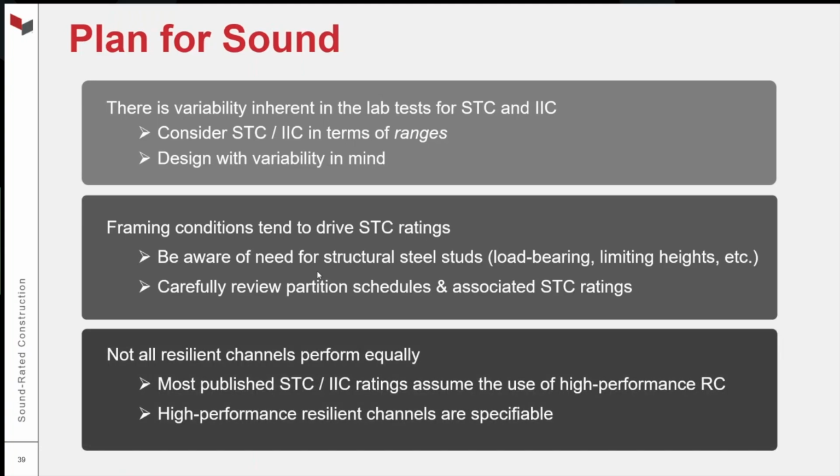And as I mentioned before, when we took that little side quest talking about resilient channels, not all resilient channels perform equally. A vast majority of published STC and IIC ratings assume the use of high performance resilient channels. So anticipate that. And if you're on the design side, these channels now are specifiable. There are 3 options. I know architects don't like to write a spec for one product or one manufacturer. Well, you have 3 options now. So I see these things as being specifiable now. And if you're a contractor, good to keep this in mind for pricing, and you do have a few different options available to you in the market.